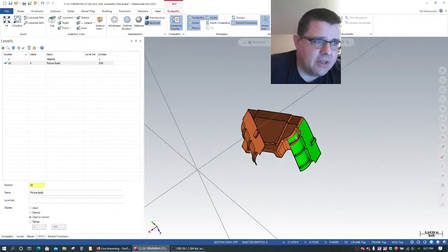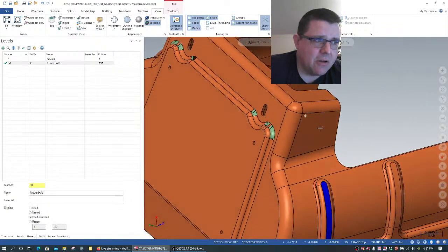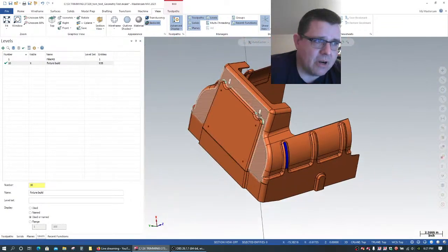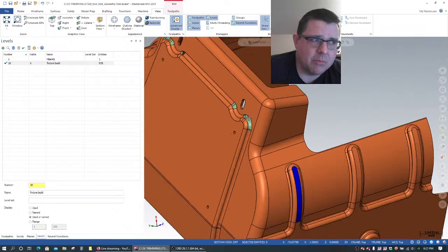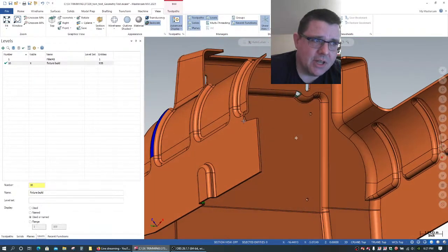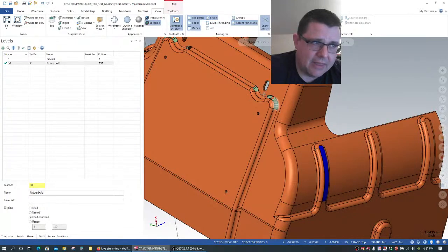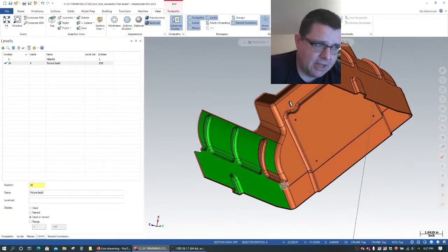So you can see that, if I'm on the outside here, oh look, when I brought it in this time, there's a lot of surfaces where they're actually reversed. So we have probably some problems, some issues with the solid in that area. I can just tell that based on the fact that it's reversed some of these. So we'll have to look at that later on the solid.